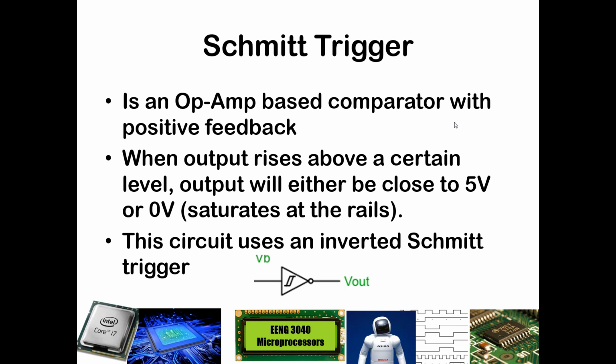So if the voltage coming in on the left side of that Schmitt Trigger is low, it will output a logic 1, and if the voltage coming in is high, it will output a logic 0. So it outputs the exact opposite. Effectively, this is built using operational amplifiers that are in saturation. It will use a comparator circuit and either saturate at the positive or negative voltage rail. In this case, the positive voltage rail being plus 5 volts, the negative voltage rail being our ground reference.